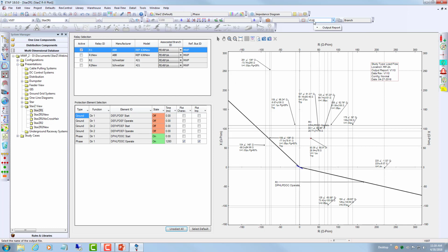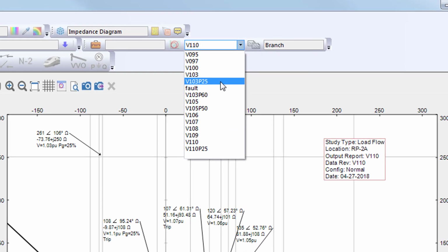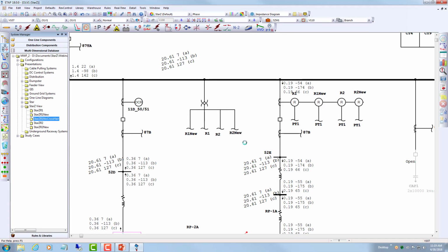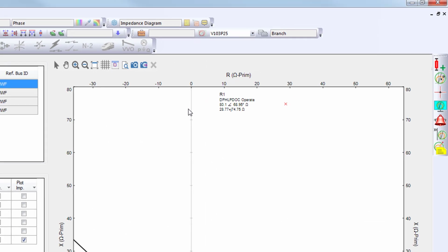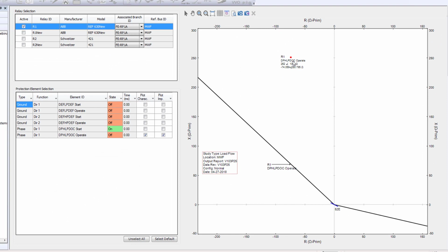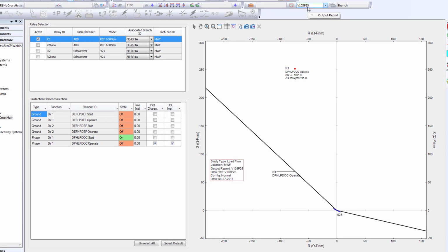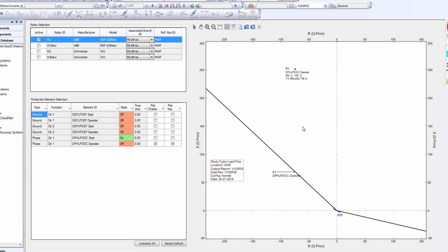Now let's look at the condition where the active power generated by the WTG is more than the auxiliary power. I've done a few cases for you. Let me go to the simple one so we have no crosshair, so you can easily see each one at a time. Let's look at 103, which is basically 3% over voltage, and the power generated by the WTG is about 25%. So it's 15% more, basically 25%, while the auxiliary power is 10%.